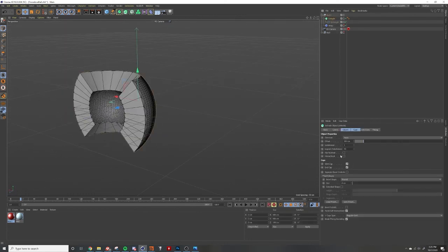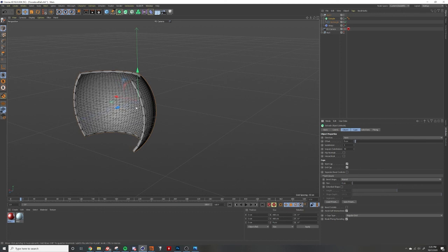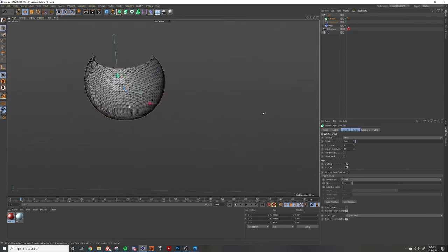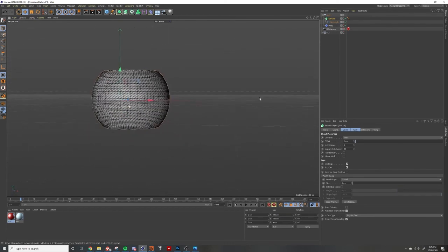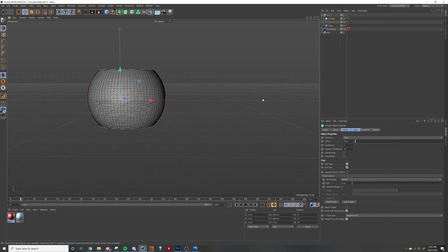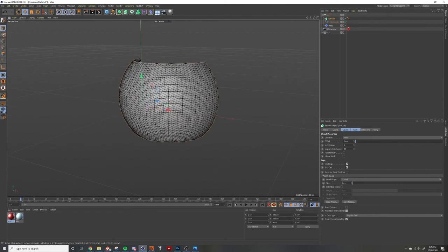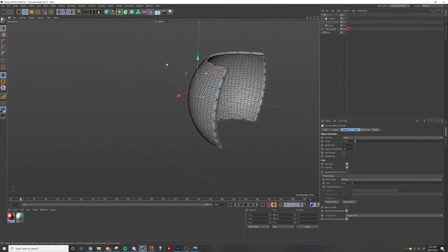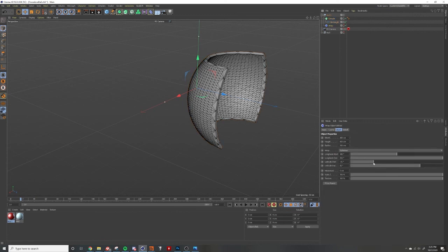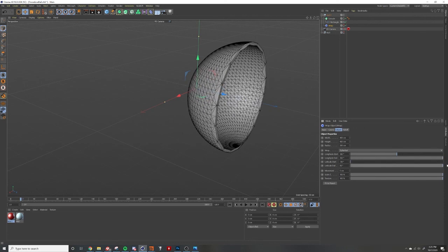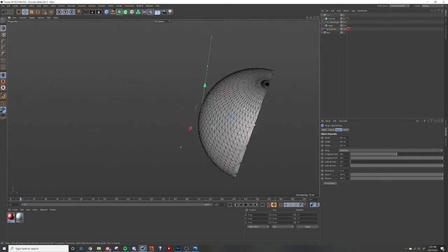sphere. Let's take our extrude, lower the offset a little bit. There we go. Now we have a nice sphere here. Now I made those nice circular holes before. Actually, what we can do is come over to our wrap quick and see this. We can just put that up to the top, and now we have a nice half circle.